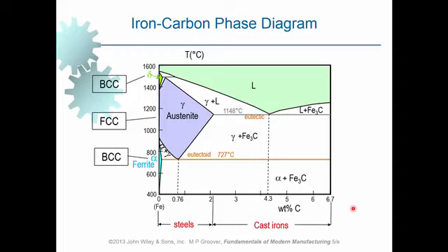The rest of it will have a lot of graphite in it. Graphite is brittle, it's useless, we don't use it, we don't show it. So it's only a section of it. Indeed, the right name for this phase diagram is not what we've got up here. It says iron and carbon. However, what we have got here on the other side is cementite, or iron carbide. Up here, we have got 100% of cementite.